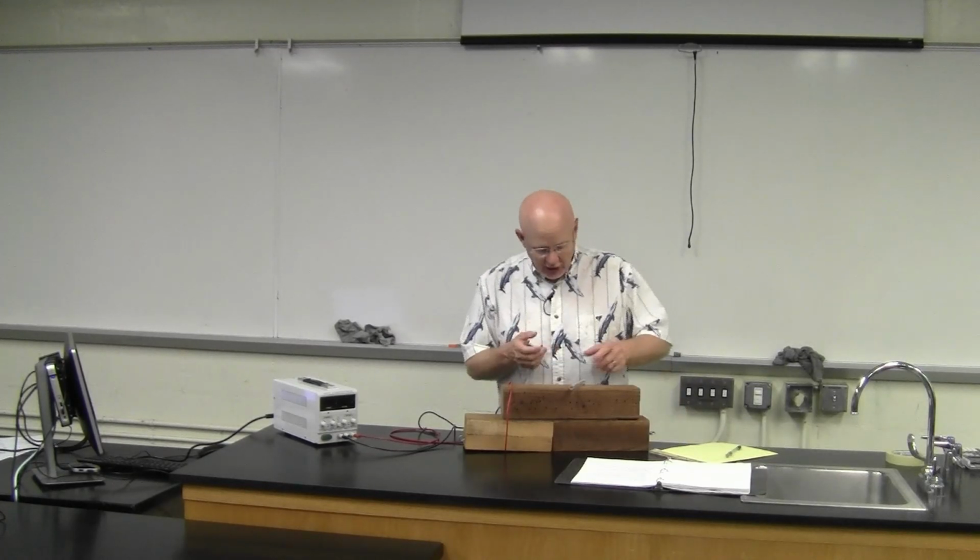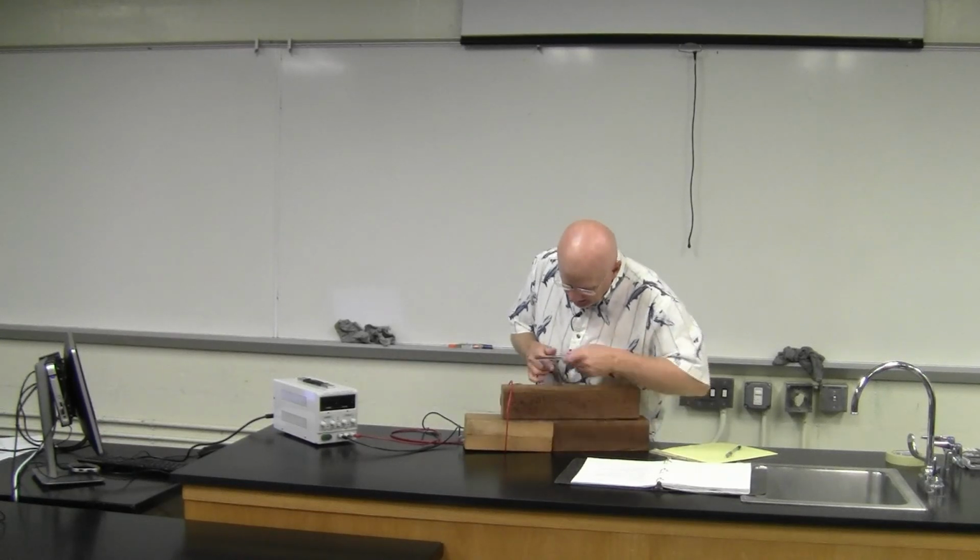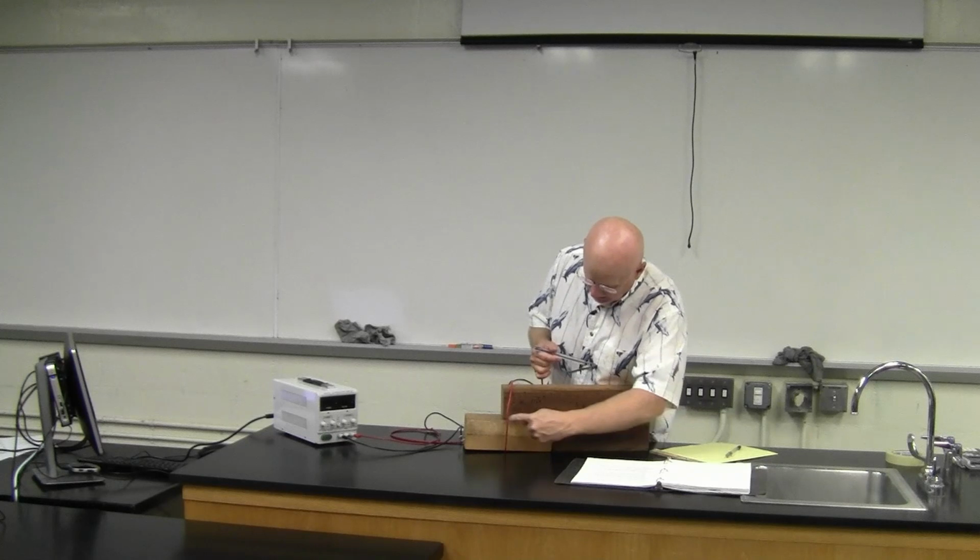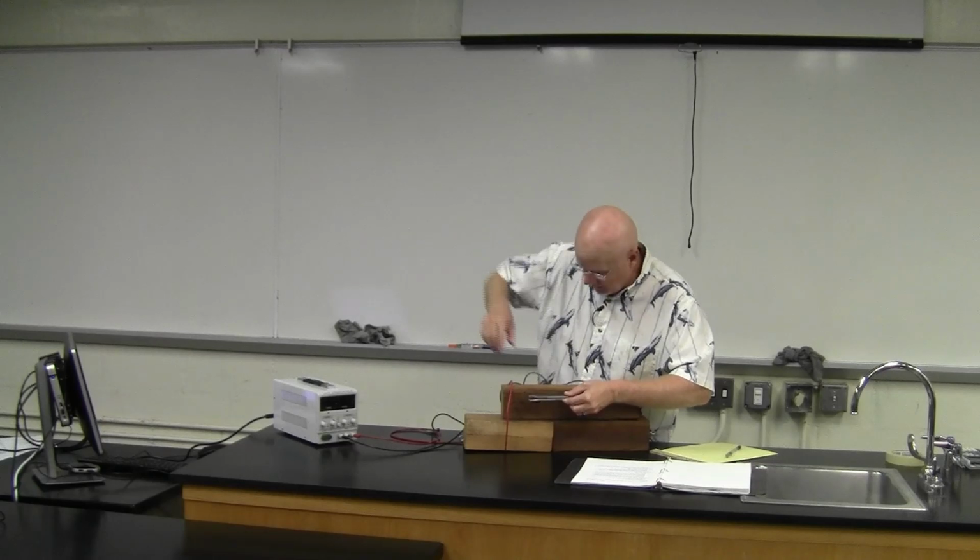I was playing with some values, and they were looking really good. And then I'll just write down, and it says to put as much current as you can with this little power supply. And so 5 amps is where it tops out at. And so you'll see when I turn it back on, it should go back to the 5 amps that I was playing with here. And then I'm just going to take this probe, and I got the 2 levels of blocks, so I can put the ruler in here, so I can just hold it at the right angle and then go along that east to west line and start moving it back every half a centimeter and see what the field strength is.